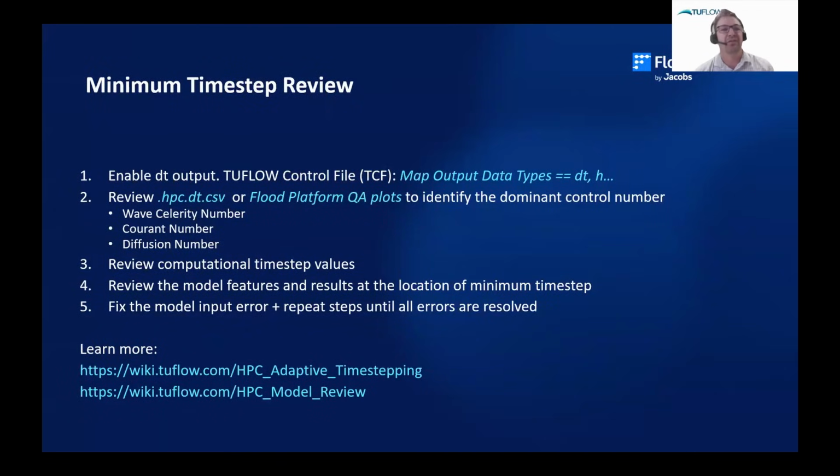The next thing I would typically review once I have a working model is my minimum time step. Now, TUFLOW HPC includes a really great feature that enables it to calculate an appropriate computational time step to maintain a stable solution. Due to the fact that the software is selecting the time step for you, review of that time step becomes a really useful model health check parameter. In essence, a healthy model will be able to run and operate at a larger time step and will run simulations faster than an unhealthy model.